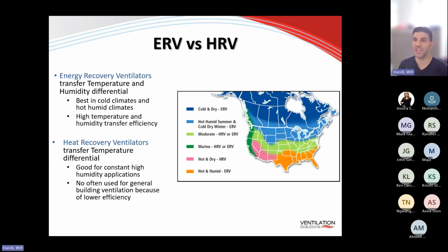Now, the ERV versus HRV. The ERVs are energy recovery ventilators, as explained. HRVs are heat recovery ventilators. Now, some people get those terminologies mixed up, so that's why I included this slide here: all ERVs are HRVs, but not all HRVs are ERVs, because what HRVs cannot do is transfer humidity.